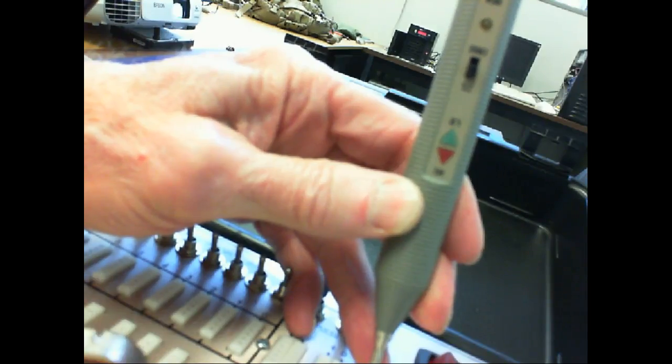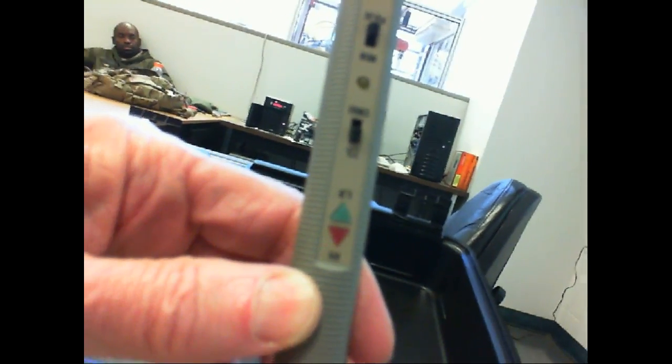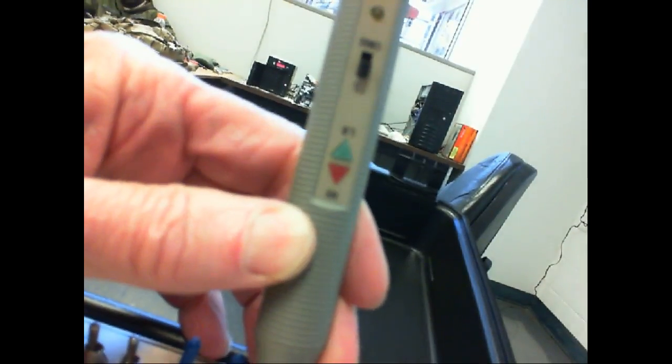So the LED's on there. I don't know if y'all can see that, but this guy right here is still telling me it's invalid. What's nice about a logic probe is it's going to tell you whether you got a legal high, a legal low, or it's invalid. If it's invalid, you troubleshoot, right? You understand, right? Figure out why it's not at least 2.4 volts or why it's not below 0.4.